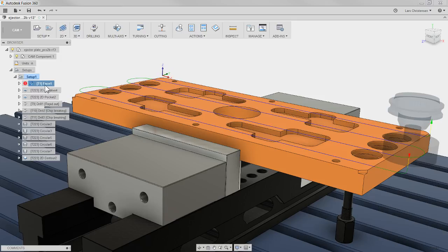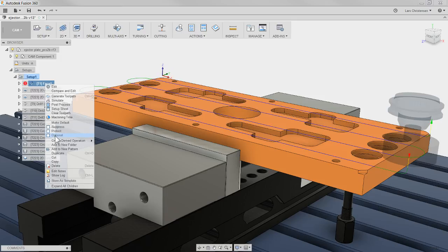The last one down here is an interesting one. It's optional. If you're not familiar with CAM, you might be like, optional what? What is my option? Optional is like when you're running at the machine and you sometimes can turn on optional stop. If you've ever done that and looked at your code, what happens is that in the machine code they put a / in front of the code, and if you have optional stop on, it will not stop. If the / is on, it will just skip past that one if optional stop is on.